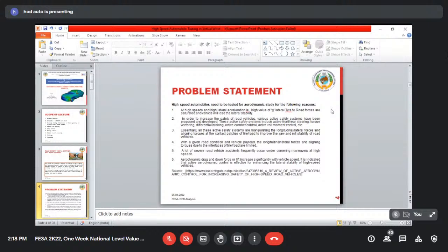If you have more drag, actually the calculation is like this. If I dump 1 liter of petrol into your fuel tank, the approximate energy you are giving is around 45 megajoules per kg. Now I have brake thermal efficiency of around 24%.